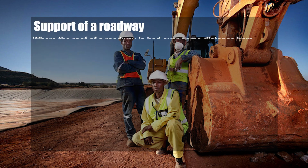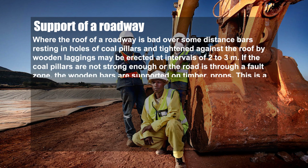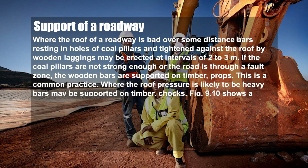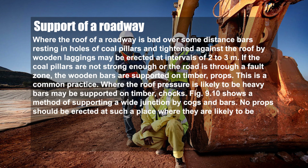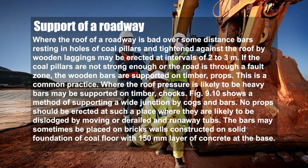Support of roadway. Where the roof of a roadway is bad over some distance, bars resting in holes in coal pillars and tightened against the roof by wooden legging may be erected at intervals of 2 to 3 meters. If the coal pillars are not strong enough or the road is rough, or in a fault zone, the wooden bars are supported on timber props. This is common practice where the roof pressure is likely to be heavy. Bars may be supported on timber chocks.